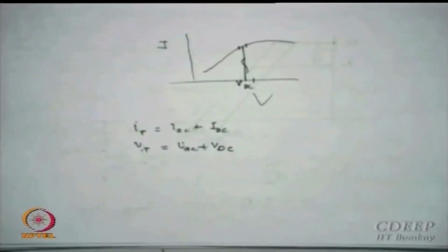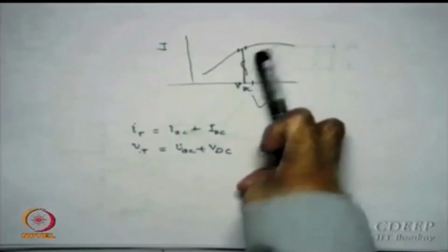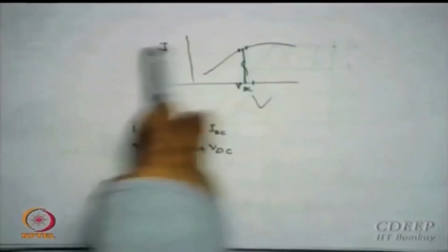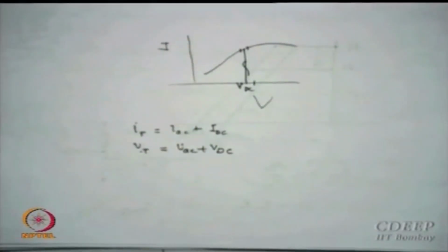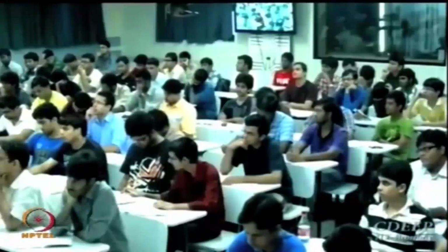The current I is so adjusted that both M1 and M2 are in saturation. Is that clear? So that is what I say, the bias point is fixed by IDC, this value. If I fix that value, I am making the device saturated. If it does not occur, yes, I will have a problem because there is no gain, then possibly I may not get enough gain, or zero gain sometimes. But I assure you, to solve this problem, that I is so adjusted that both devices enter into saturation. Is that clear?